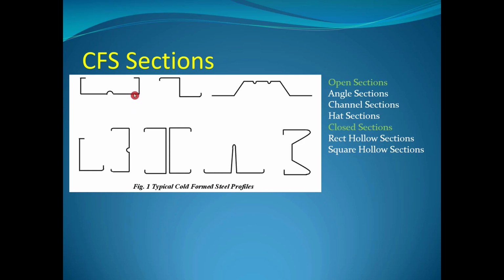So these are the different cold form steel sections. This is a channel section. Just neglect this portion; this is actually called the stiffening. If you neglect this one, the channel section will start from here and come straight to the right portion. This long length doesn't have any support from the sides in comparison with its length, so this is a way of stiffening this web member.